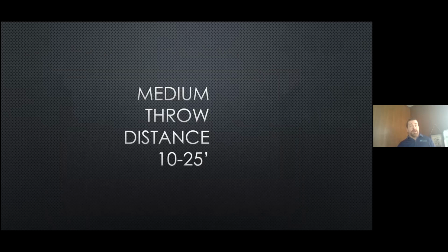Typically, what you're going to be seeing, and this is where most people are going to be incorporating fabric, will be higher ceiling applications with longer throw distances. Typically, what we're running in is like a 10, 20, sometimes maybe a 30-foot throw distance. And in that case, and this is, again, kind of a generic thing for all manufacturers, we move into standard perforations.